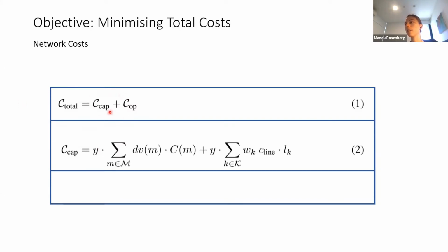Typically we have capital costs and operational costs. The capital costs are the cost of the infrastructure that I need to build this network. As soon as we split off a network part, some consumer, we need to install some kind of source of generation. I'm assuming the approach that Horizon Power is taking, so we have generation from solar panels with some storage and a backup system.